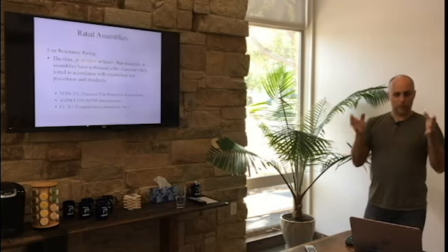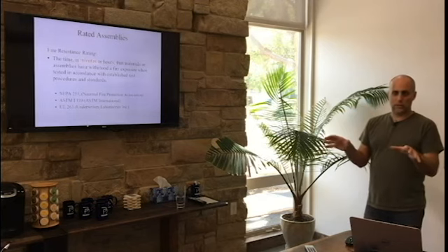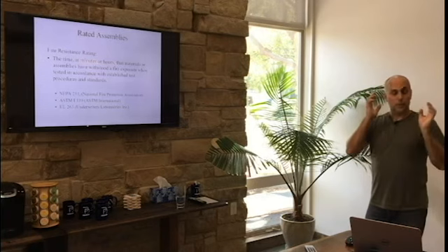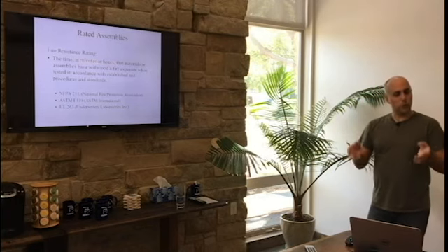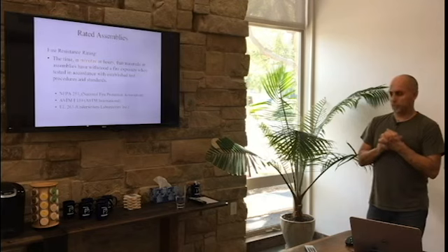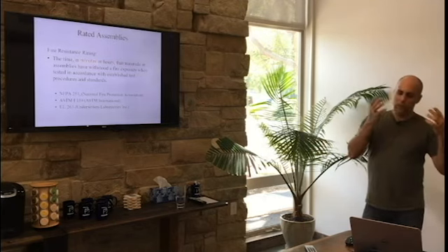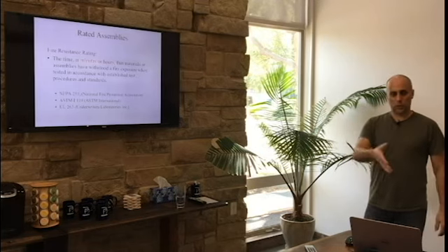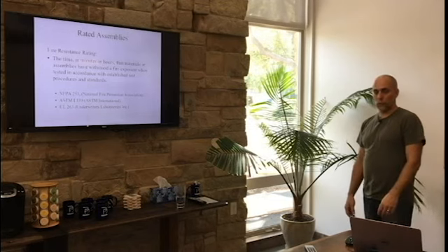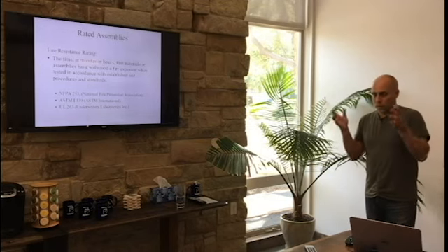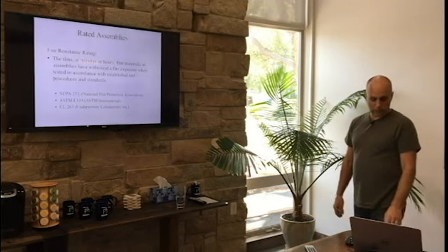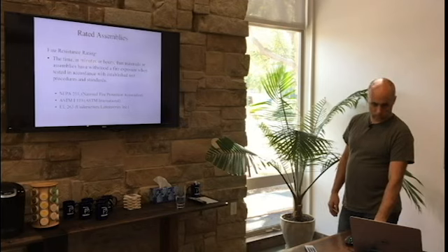They test it for 1 hour. Great, it passed. They stop the test. They don't burn it for as long as they can and say, let's see how long it lasts. No. You want an hour, you got an hour. If you want it for 2 hours, great, we'll test it for 2 hours. If it doesn't meet 2 hours, nope, doesn't pass. Once it's passed, then they describe basically the assembly that passed. That is now the assembly that goes into UL's directory of assemblies. So everything that's in there has physically been built and tested in a laboratory, and it has passed the test.